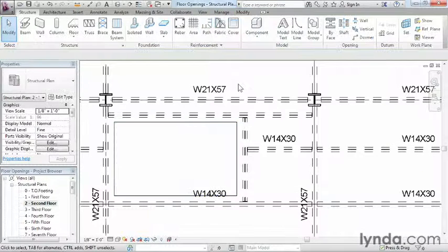Now here on the second floor, we have the proper structure in place, as well as an opening in the floors. So it's now framed around and it's going to be structurally sound. So in conclusion, shaft openings are objects that can be moved around, and they'll create penetrations in each floor plate of each floor that they happen to extend through. Just remember that if you're going through this process, you're still going to have to make changes to those different structural conditions that frame around them.